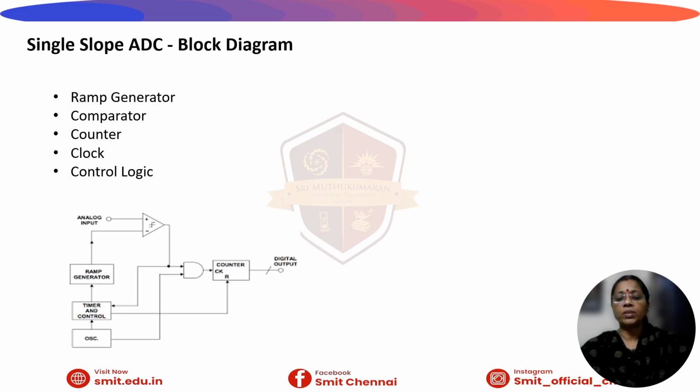The conversion process takes place in three main stages. The system's binary counter and the ramp generator are both reset to 0. The ramp generator outputs a linearly increasing reference voltage, which is nothing but a simple integrator. At the same time, the digital timer counter starts counting the clock pulses.